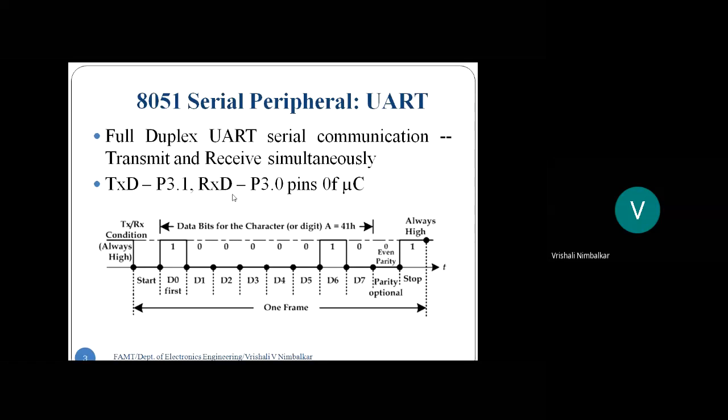Is that okay? And now, if nothing is getting transmitted on those TXD, RXD pins, it means it's idle. No transmission is going on. So idle state means always logic 1 appears on the transmission and the reception. Right? So if nothing is getting transmitted, what appears on TX-RX?